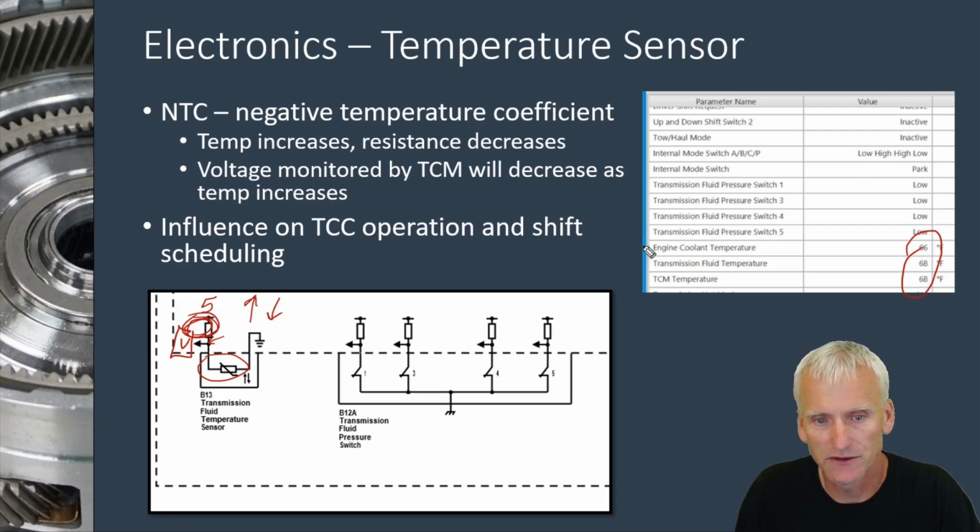And this shows the picture on the side here of a few different temp sensors going on. We got engine coolant temp, transmission fluid, and then the TCM. The TCM lives on this example. This is the 6L80. All these little data streams that I've got up here are just snippets from a 6L80 off of a 2014 Silverado that we've got at school.